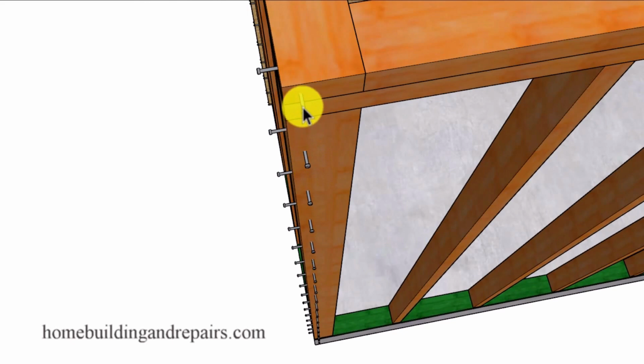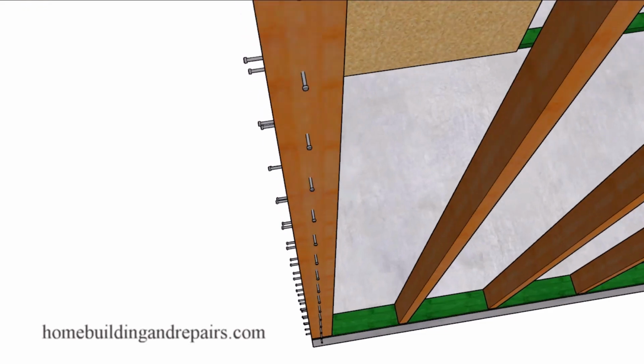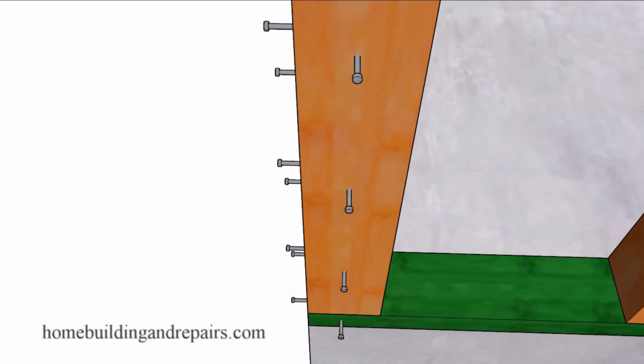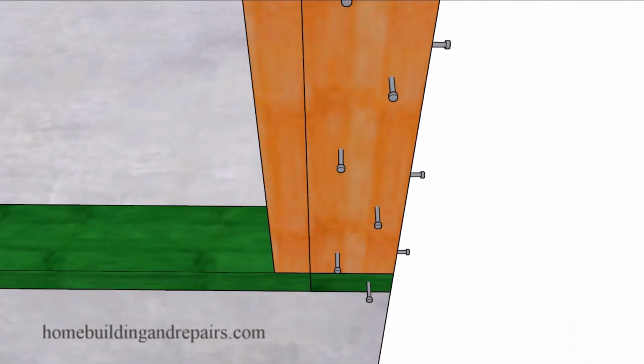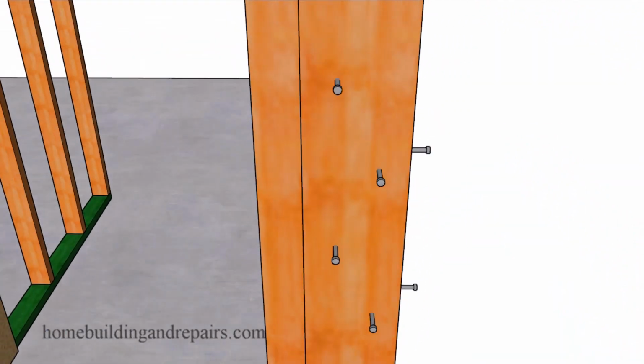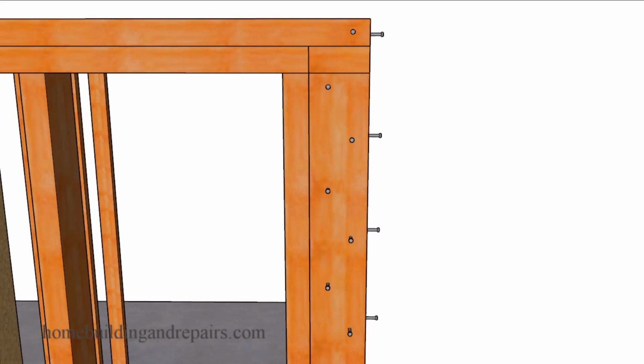If we were to put a bunch of nails like this into a 2x4, and we're going to put all of these nails in the same spot going all the way down, you can see where something like this could split the lumber, and I've seen it done before. And if that's the case, you might consider staggering the nails. And this might actually be something that the engineer will require on the building plan.